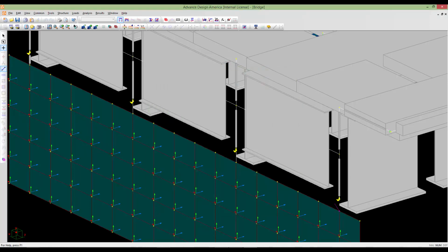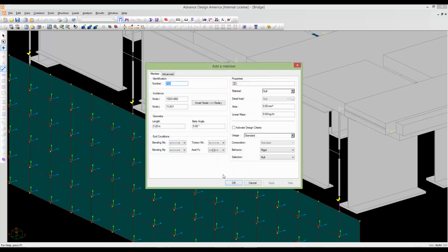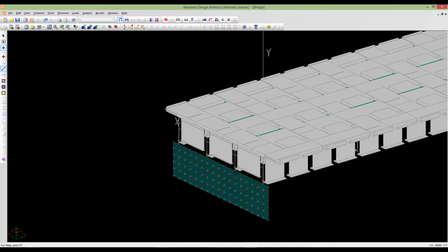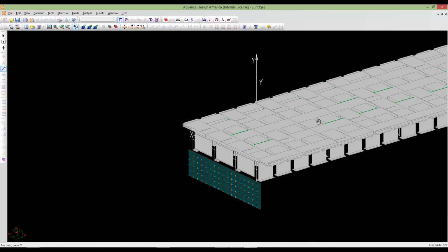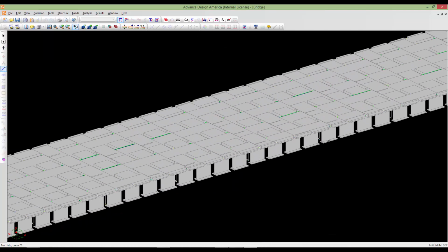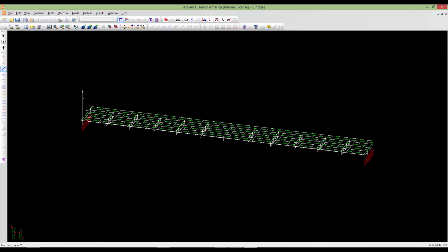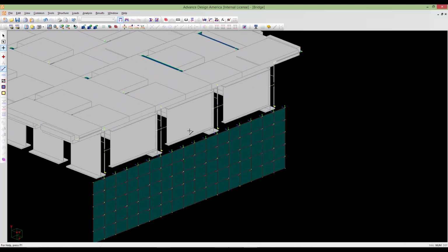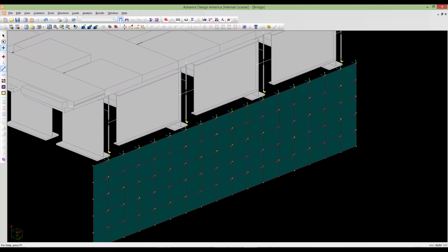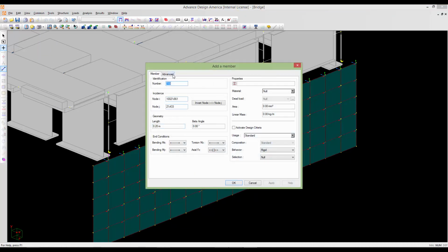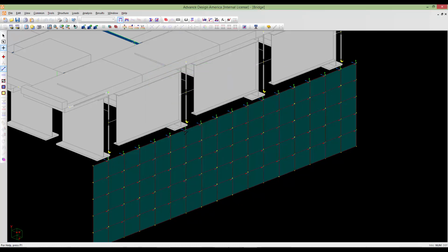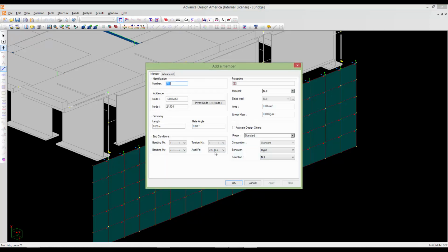And the final girder. Also, we are going to define the same rigid links in the opposite abutment, the other abutment. So click the nodes from the wall to the girder, stage 3, rigid, OK.